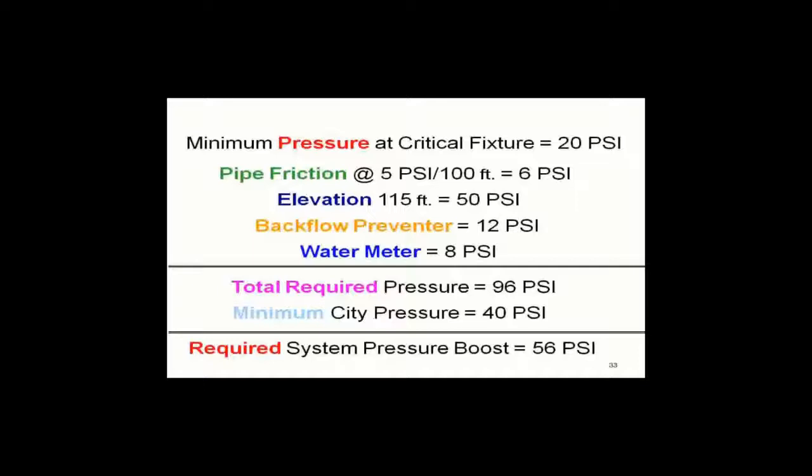Remember, we had to have friction loss. Our max allowable pressure drop per 100 feet is 5 pounds. So if I look at that chart, I had about 110 feet of pipe roughly. So I'm going to say under full flow, I would not exceed 6 pounds. Maybe a little heavy with the 6 pounds, but that would potentially be my friction loss.